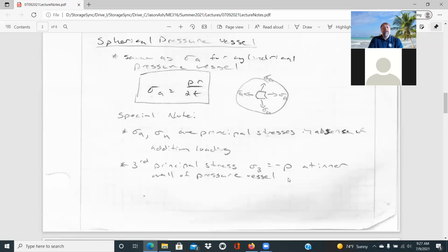But in terms of inspection, that can make it difficult to identify when failures are beginning to occur. And so they have different X-ray methods to identify those internal cracks. For other applications where it's a super large pressure vessel, they'll evacuate all the contents out of the pressure vessel, have people go in and visually inspect the inside of the pressure vessel to see if any cracks are forming and if they need to be repaired at all.